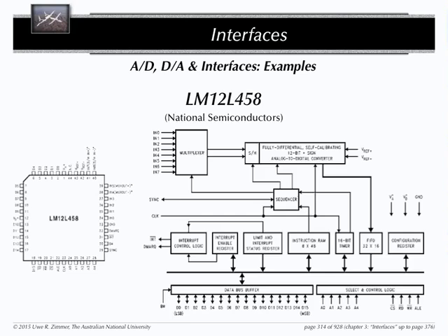And this address decoder goes directly into the chip select, activates this interface, and this thing can talk to the bus. So only if chip select is active, this thing is allowed to interact on the bus. Right? What it does internally, where it reads from, where it writes from, is controlled by the address lines. And you need a few more lines to communicate on the bus, namely, you have to tell them, is it read access or is it write access? You have to tell this device in which direction it's supposed to drive the bus. Right?